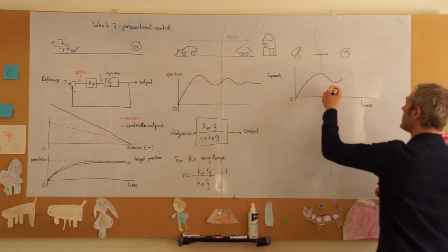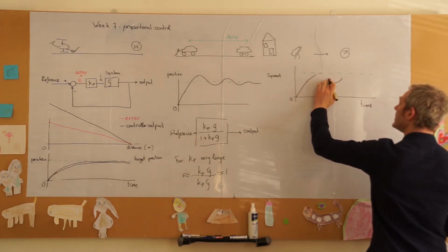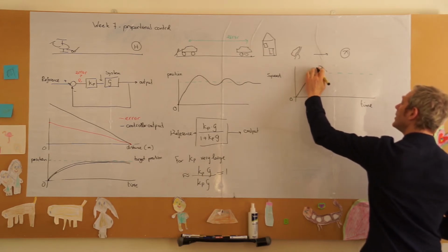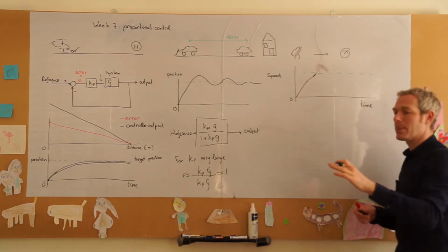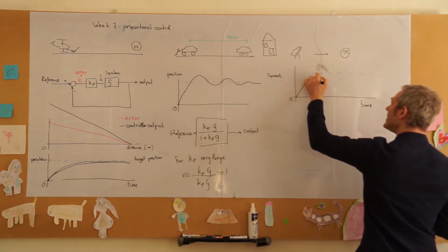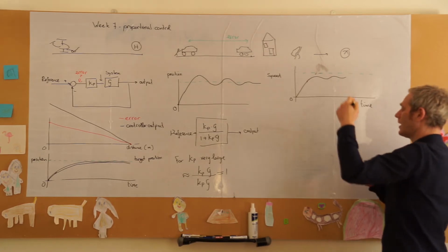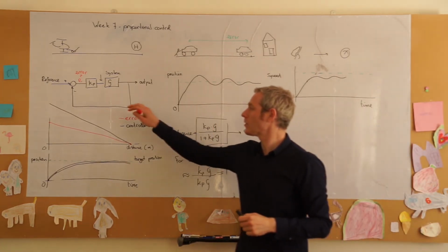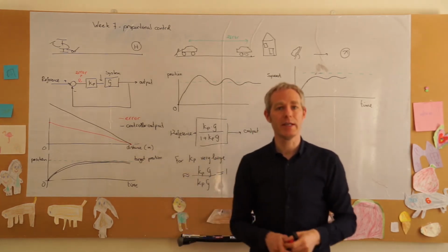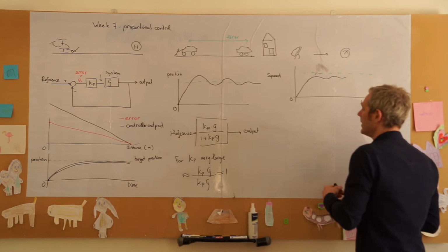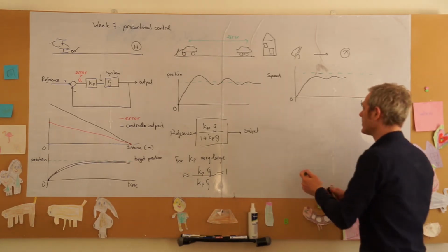And if there's some momentum in the system, we will also have these oscillations, or we will simply take our foot off the throttle and never really reach it, and we end up oscillating and never getting there. The problem with the proportional controller is it doesn't have any memory. It doesn't know to keep the throttle in a certain position. So there's three problems. Well, how do we solve it?